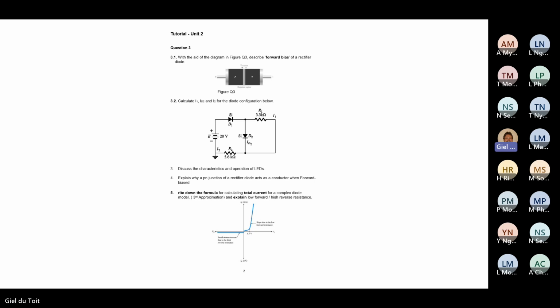No, pen, not lasers. 0.7 volt divided by this 3K3. Very ugly, that 3. So let me do it again. 0.7 divided by 3,300. So it's 0.21 milliampere. You got it. 0.2, or 0.21 if you want to, for more accuracy. 0.2 is not very accurate. So that's how we got that current.